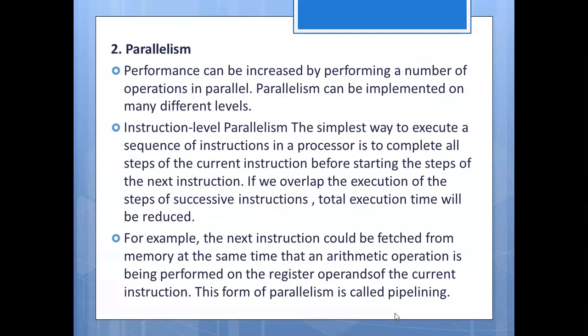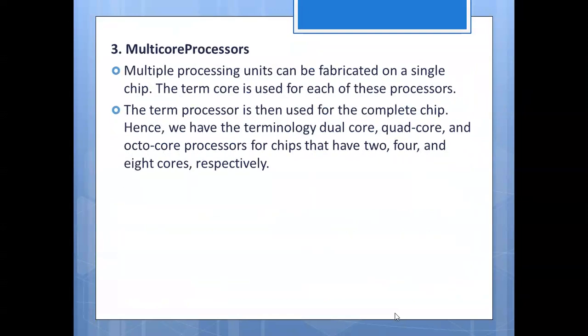For example, A plus B is being performed, and the next operands to be loaded are fetched and getting ready for the next operation. Once the first operation has been done, immediately, in the background it is doing the fetching operation, and the execution is carried on in parallel. This type of parallelism improves the performance of a processor, as well as reduces the time taken to process.